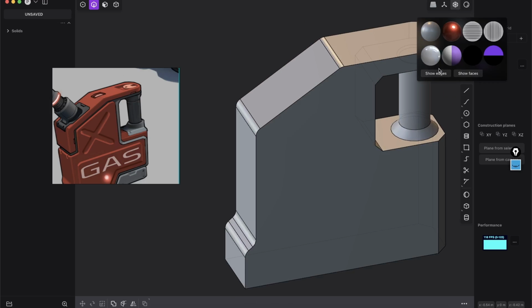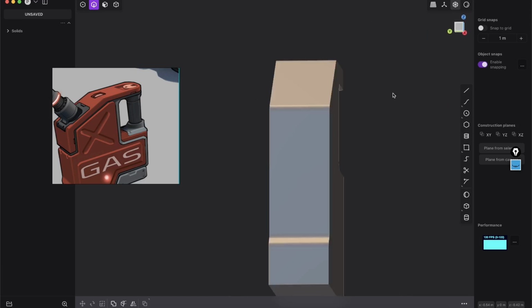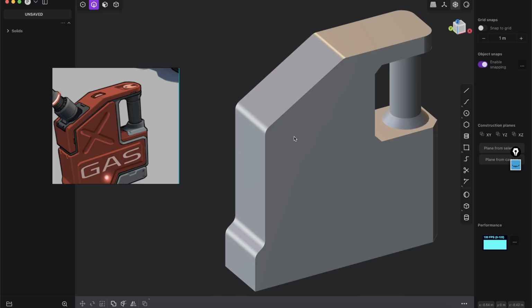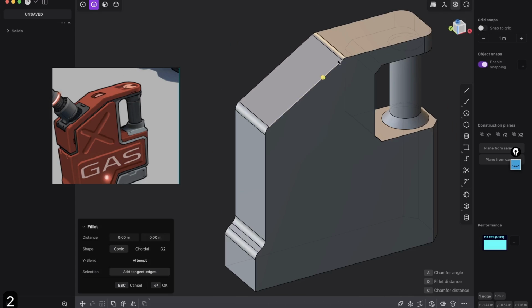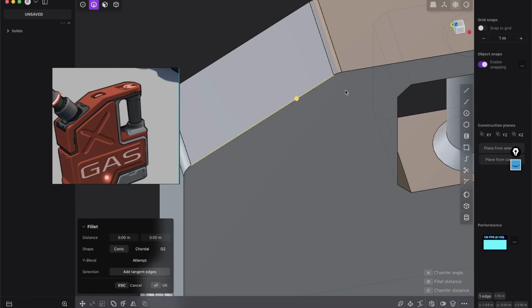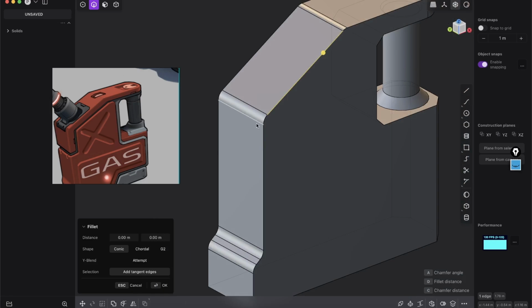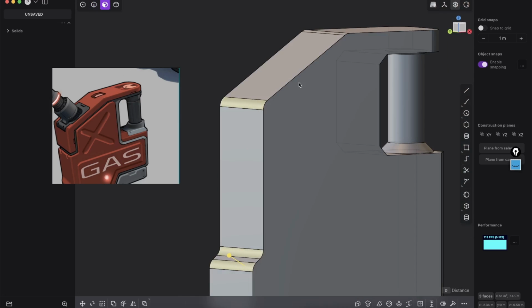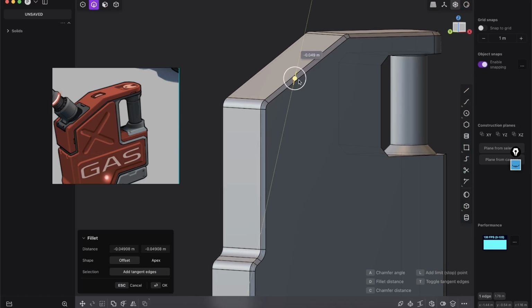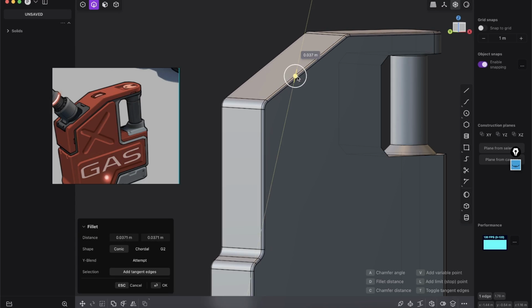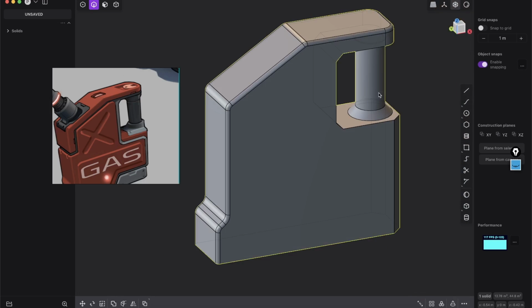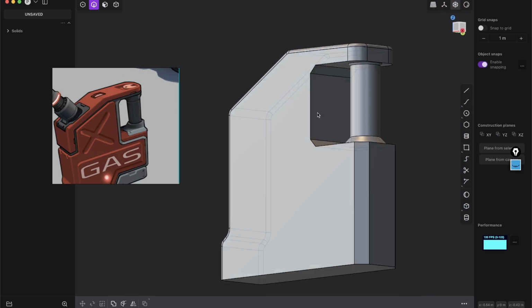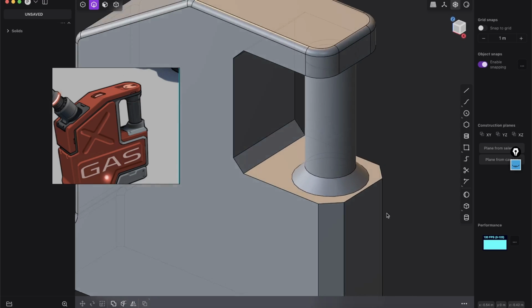So you can press here right click and show edges. So you can toggle, and then you can just see a little bit better how it looks. And so again, right click here and then again show edges. And again, let's select this edge, and you see you don't have to select every edge, because if they are smoothly connected with those fillets like they are right now, you just can select one edge. And if you fillet that, it will just go completely around, and that looks beautiful. Perfect. So let's do the same here at those edges.